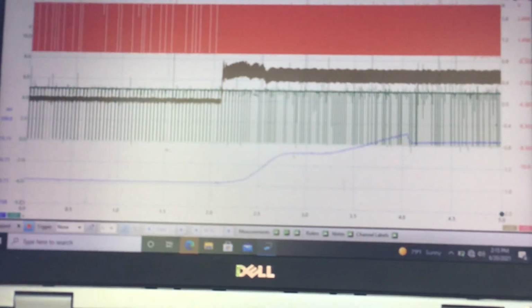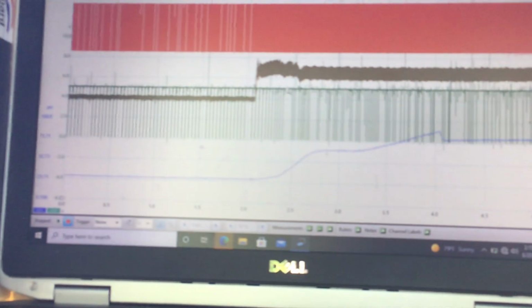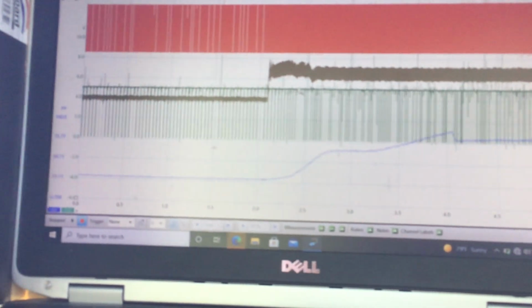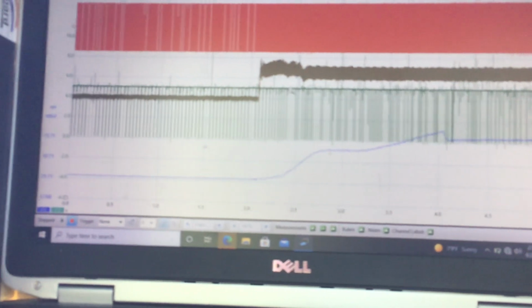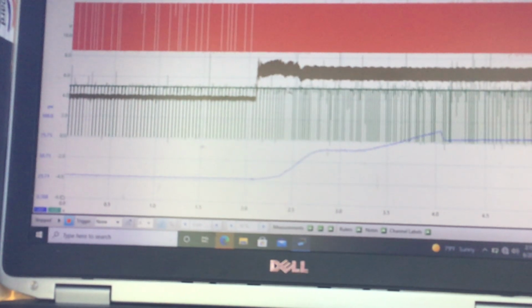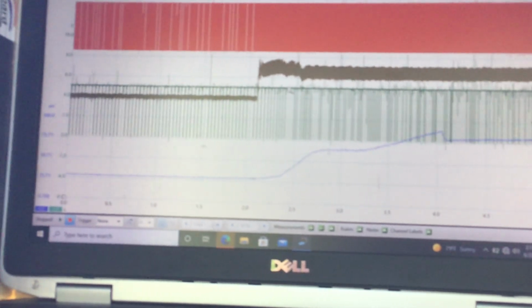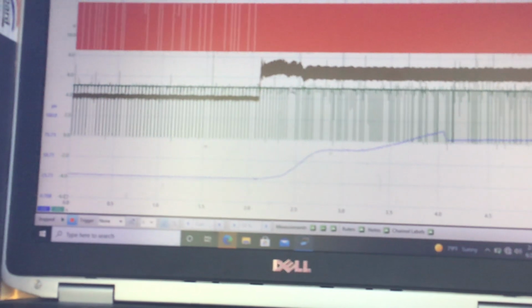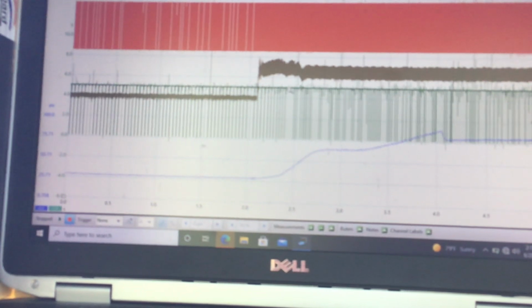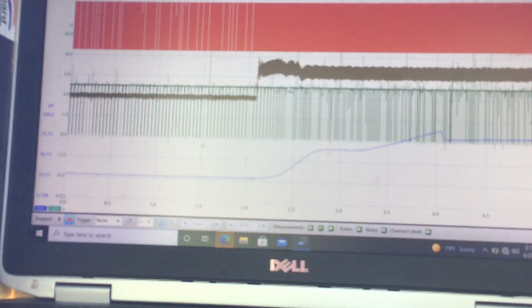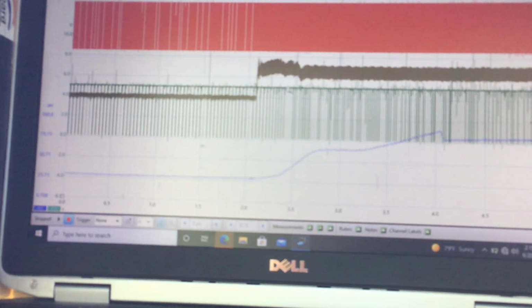make sure oil pressure is up to snuff. Even if the engine didn't have variable valve timing, oil pressure is critical, but nonetheless we want to be careful that it all starts with oil pressure as far as phasing those cams. I think of that Triton 3 valve by Ford. I've heard that you have to be north of 30 psi when it's idling and hot for that system to function properly. That has a myriad of different issues as far as variable valve timing, phasers and things related to timing. So always be mindful of oil pressure when we deal with a variable valve timing issue, whether it's from a performance issue, a check engine light, or a code.